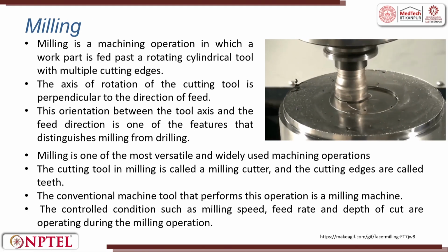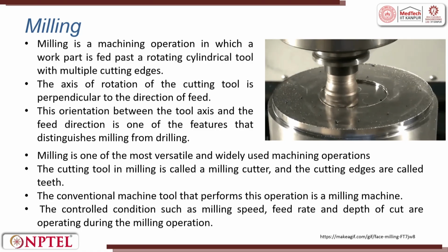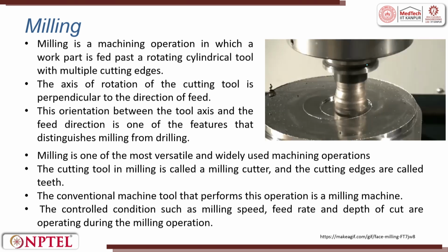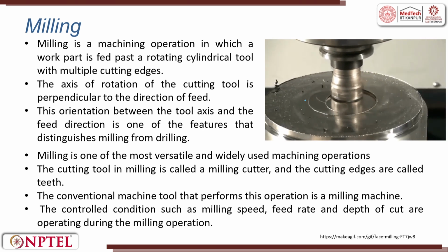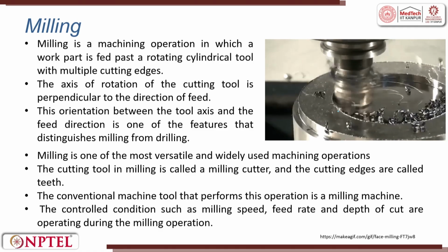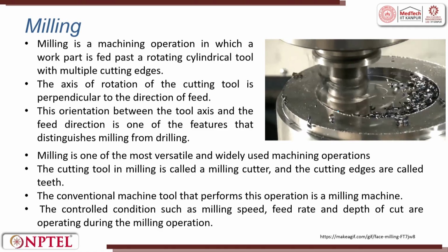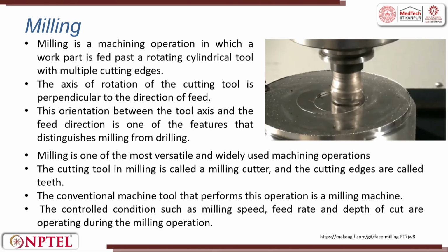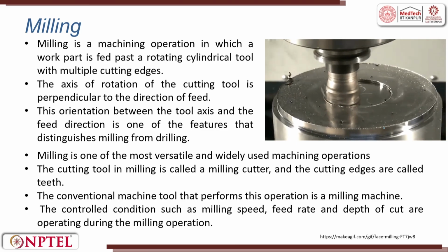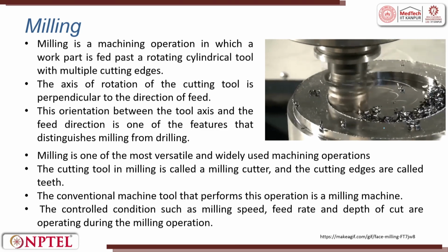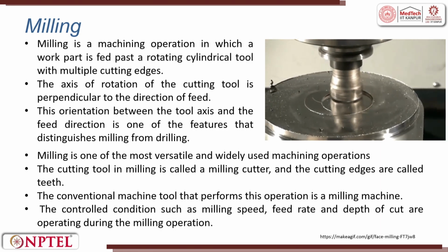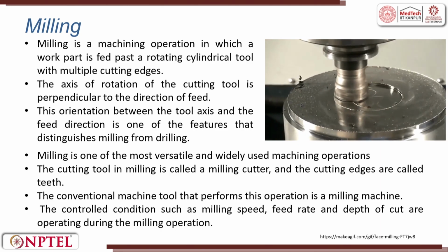If you see this video, it clearly tells you that a cutter is going around on a fixed workpiece. The cutter rotates at a very high speed, so you are not able to clearly distinguish multiple cutting points. And here, if you see, there are chips produced, and the majority are discontinuous chips, as compared to your lathe machine where you had continuous chips while machining ductile material.